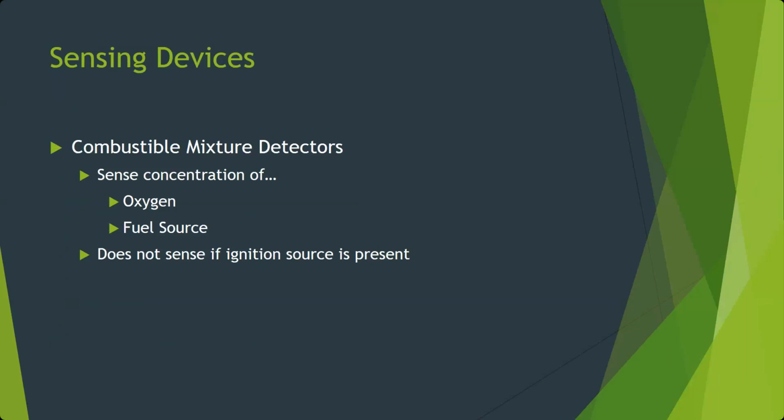But it doesn't take much of an ignition source if you have a truly explosive atmosphere. It can be as much as a little bit of static electricity jumping from one spot to another, or a little tiny fuel level sensor wire that gets chafed in a fuel tank and causes something like TWA Flight 800 that ignited the center tank.